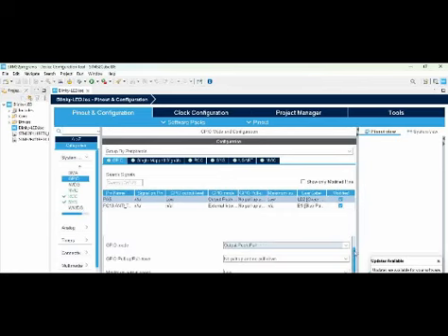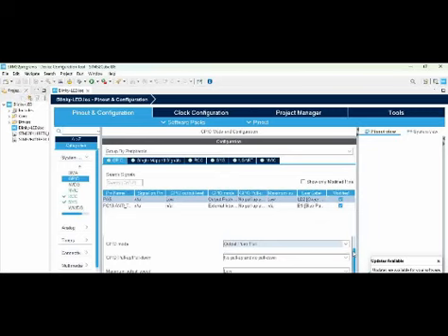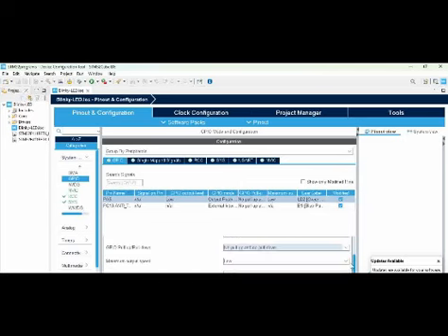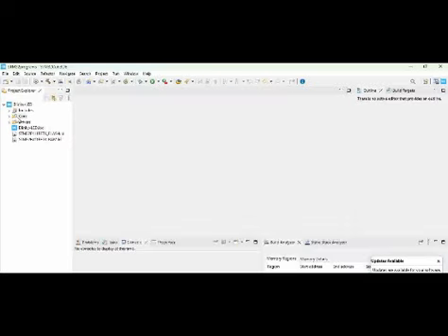As you are configuring this particular pin for toggling, you need output push pull, and you are not going to use any pull up and pull down, so you can keep it as is. Maximum output speed, for now we are not too concentrated on getting accurate speed of the LED. We are just trying to make it high and low, and that means your entire configuration is ready. Right now close this.